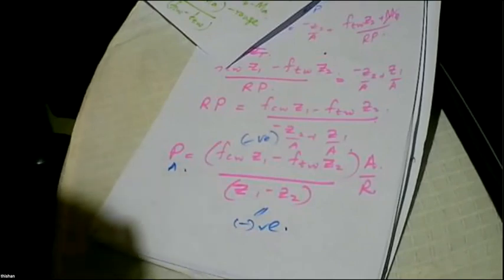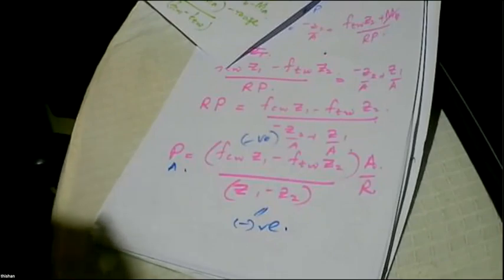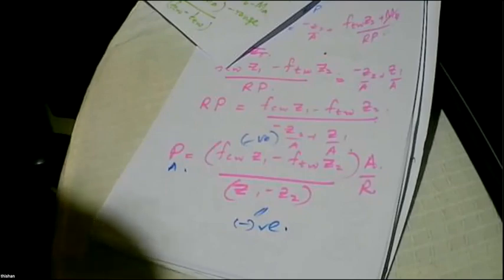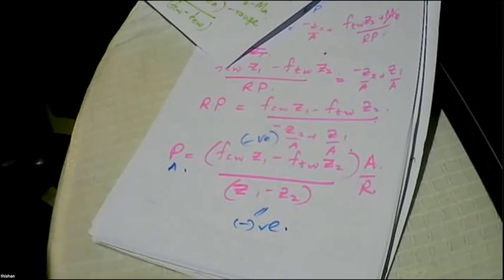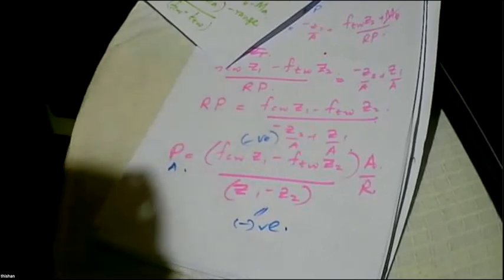So what I have shown is that the Magnel diagram is a pretty strong tool, and it is applicable for the simply supported case. It's applicable for composite section. Now you have seen it's applicable even for a continuous one. But you have to be a little careful because some of these things would not appear as simple as this, and that's what people found the hard way. Although they thought, okay, it's so simple. Later they found it's a nightmare designing a continuous bridge.